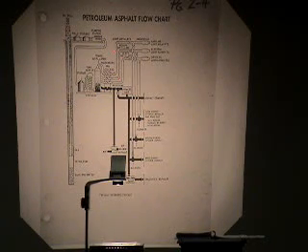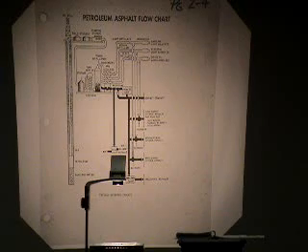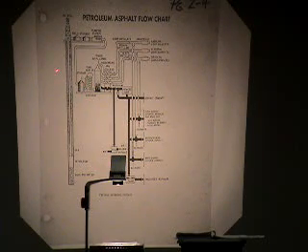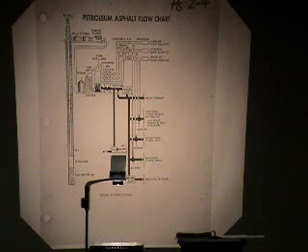The next thing would be your kerosene or light burning oil, and then our diesel oils and light and lubricating oils. And then down at the bottom of your distillation tower, the residue that is left is our asphalt binder. As you can see here, they call it asphalt cement. This is an older overhead, but the asphalt binder or asphalt cement comes off.